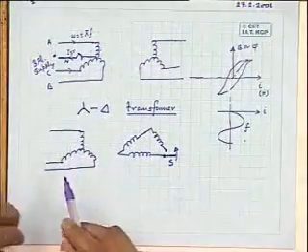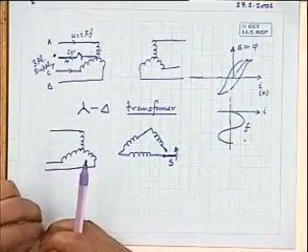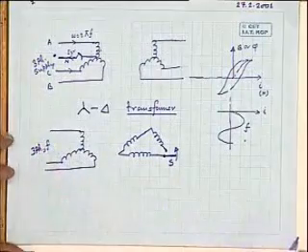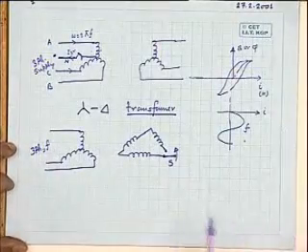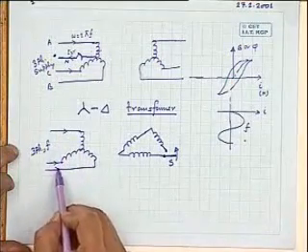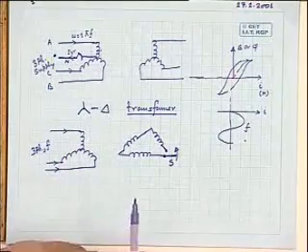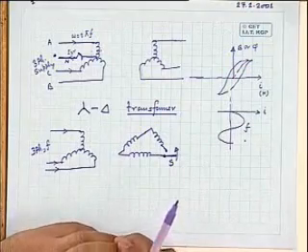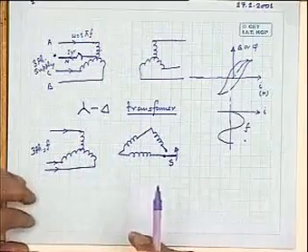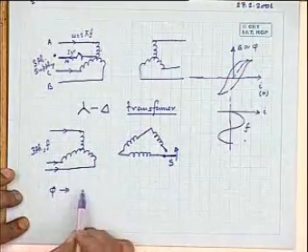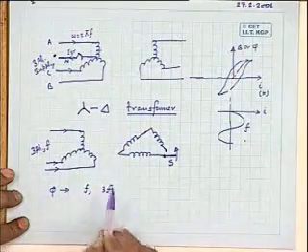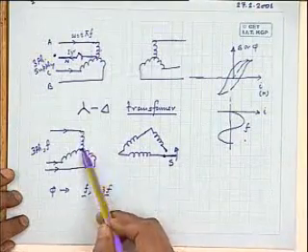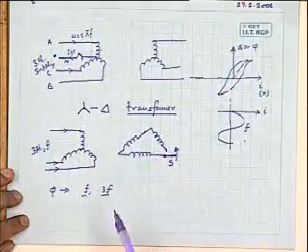Suppose this primary side, which is connected in star, is supplied from a supply frequency f of 50 Hertz. Tell me, under this condition, what will be the nature of the flux in the core of the transformer? Will it be sinusoidal? It will be flat topped. That is, the flux distribution in the core will have a fundamental component. The flux in the core will have frequencies F and 3F.